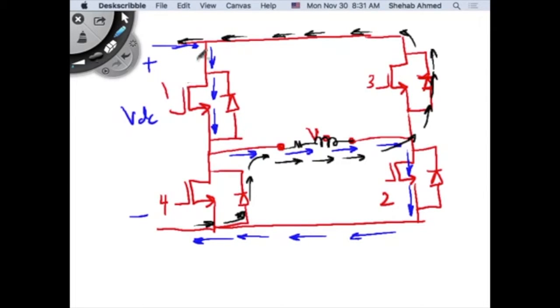And it makes sense. Current has flipped polarity in the supply. My supply current has flipped polarity. So this is the freewheeling time. During the dead time, current is freewheeling through these diodes, the freewheeling diodes. So this is, let's say, S1, and then this is D1.